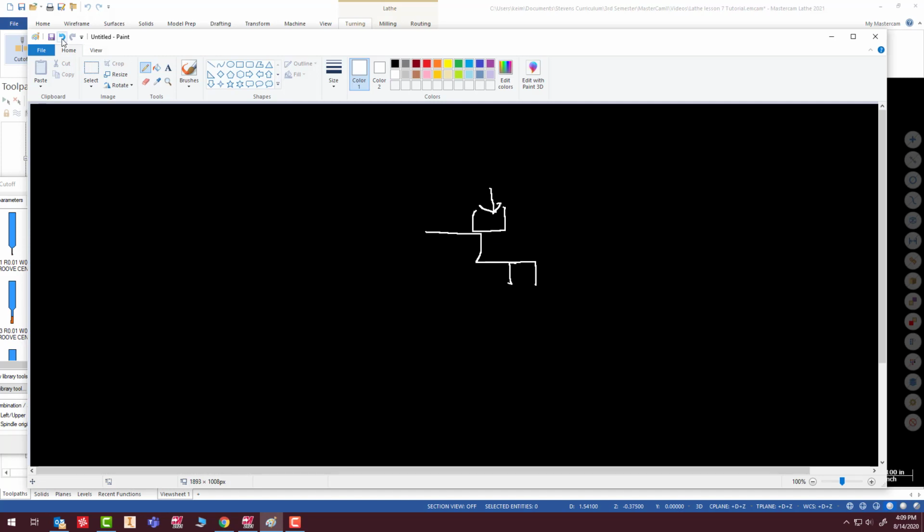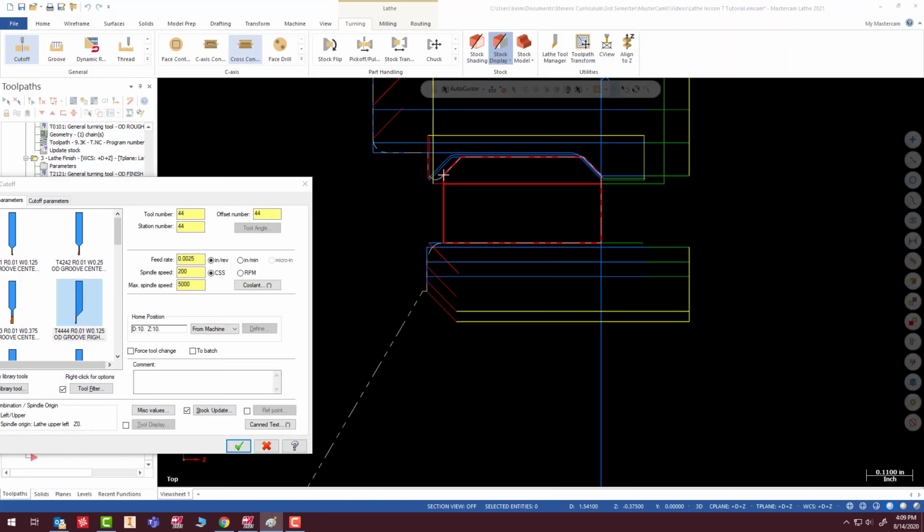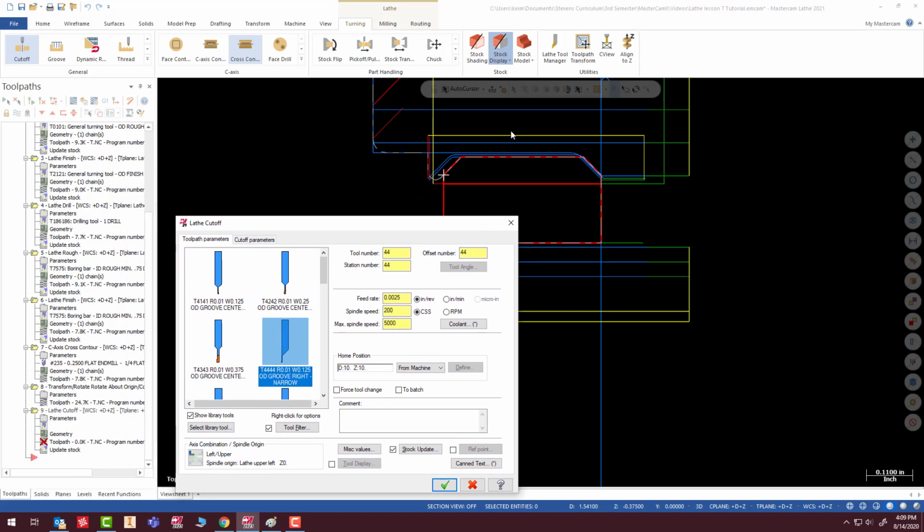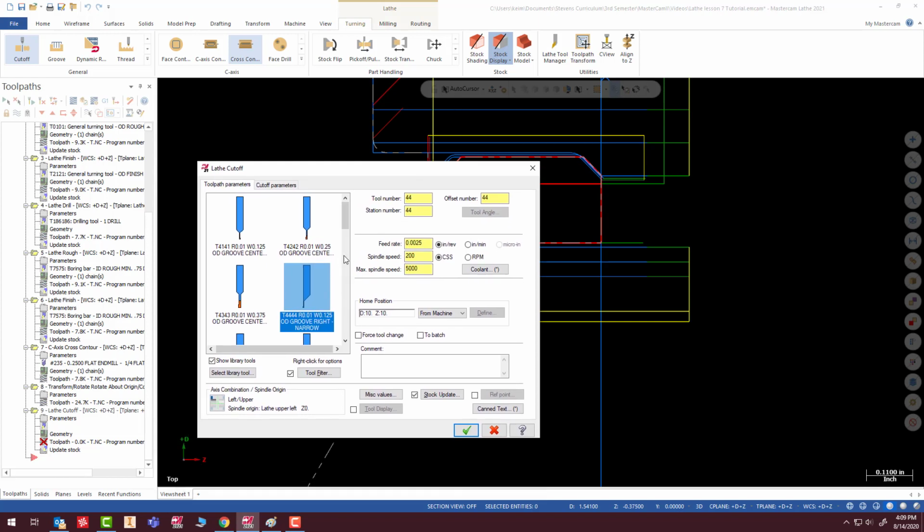So what I really want this to look like is something like that. Now I don't have to worry about this deflecting because it's just hitting this flat surface. So that's the reason that we do that. That's something to think about: why you're going to have to rough this further than you really need to. And of course, we wanted clearance for our finish tool, and we needed clearance for that end mill too. So actually I ended up extending it further for that reason.